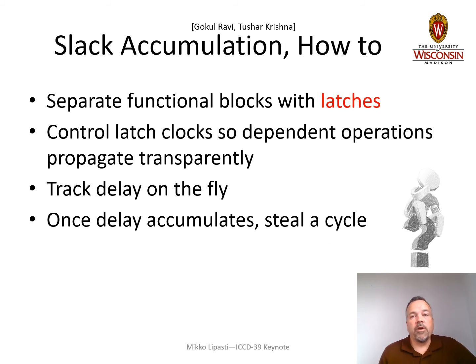So at a very high level again, and this is PhD work from Gokul Ravi, and we did some collaborations with Tushar Krishna from Georgia Tech as well on this. But the idea is to separate the functional blocks in your pipeline with latches, just like you would in a normal design, but control the latch clock so that dependent operations are actually there concurrently, and the computation can proceed from one block to the next in an asynchronous way.